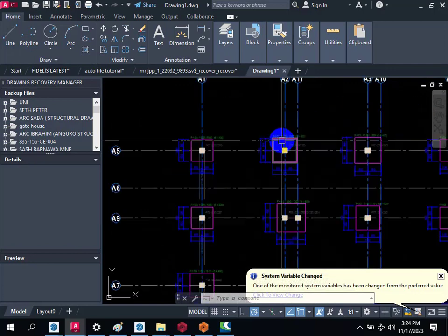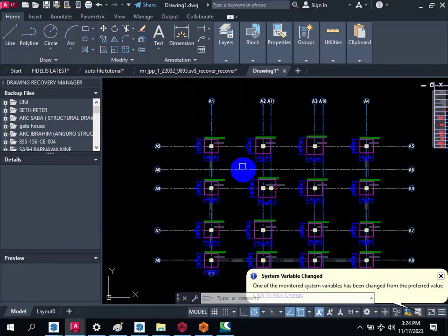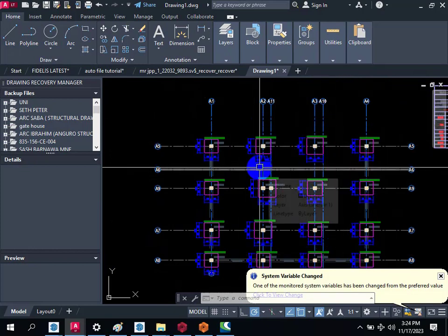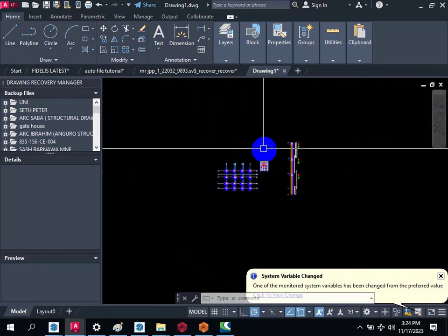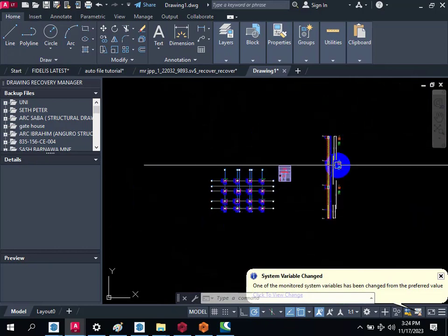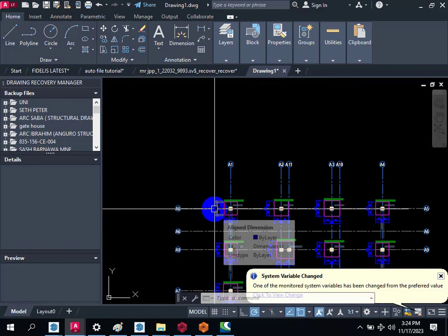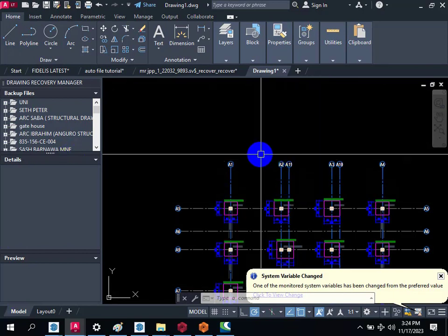Because if I'm to do this detailing manually, I may adopt just one type of column for the entire building. So in that case, you can just have one column, except where the cross-section is different, or the length, because we have columns that can terminate on the ground floor and columns that can start from the first floor.